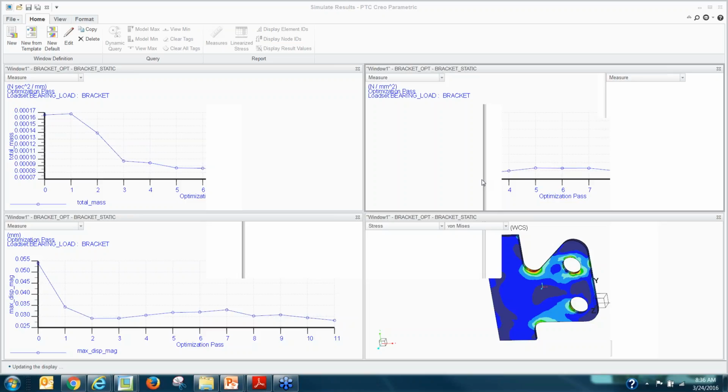The next question: is mold flow analysis a different product, or is it an add-on to Simulate? Yeah, it's a different product. That's more for the plastic mold. It's more for the manufacturing side, where you want to simulate the actual flow. Is there any air trap, vents, things like that? So that's different. It used to be called Plastic Advisor, but PTC no longer uses that old Plastic Advisor. It's a different product starting with Creo 3.0.